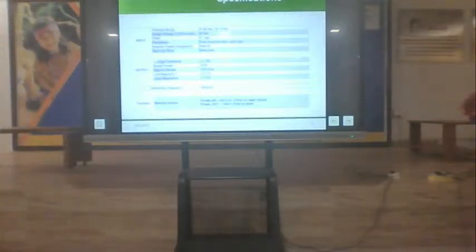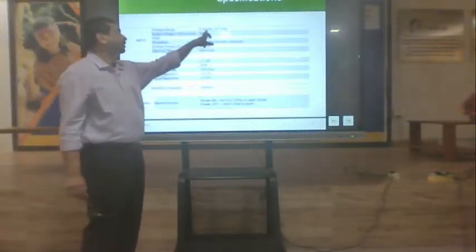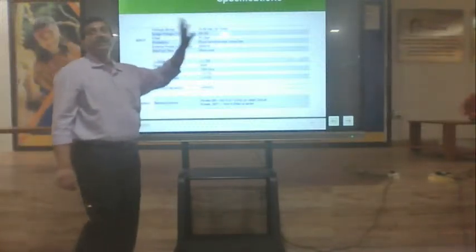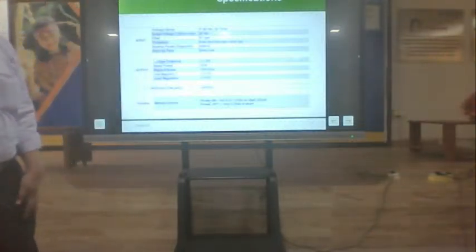First will be the input specification, and the first thing is the input voltage range. This is the range between which the DC-DC converter will deliver the required output. Say I want a 5 volt DC-DC converter, like the example given here. It takes 9 to 36 volts as input and delivers a constant output of 5 volts.